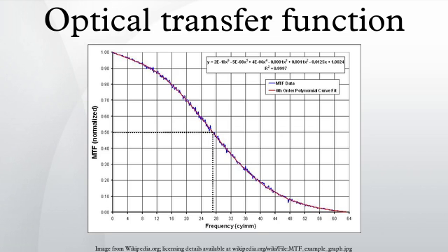Oversampling and downconversion to maintain the optical transfer function. The only way in practice to approach the theoretical sharpness possible in a digital imaging system such as a camera is to use more pixels in the camera's sensor than samples in the final image, and downconvert or interpolate using special digital processing which cuts off high frequencies above the Nyquist rate to avoid aliasing whilst maintaining a reasonably flat MTF up to that frequency.